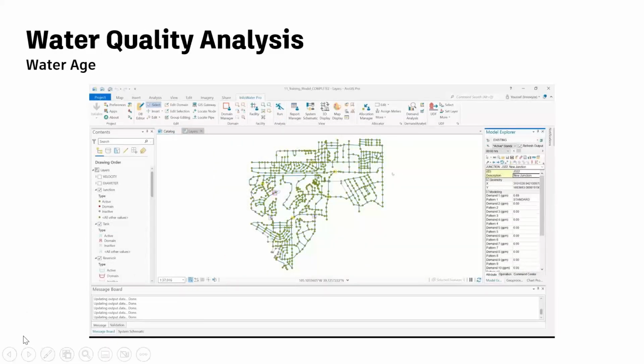And so these first 3 slides that we covered just focused on fire flow analyses and everything pertaining to fire flow analyses within InfoWater Pro. So I just showed you the ability to do single fire flow runs, multi-fire flow runs, and develop hydrant curves in a very streamlined fashion. A lot of these videos were 15 to 30 seconds, and that's pretty much how quickly it is to generate or to run any of these scenarios.